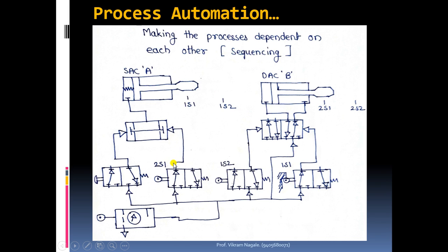I'll take you step by step to the final logic. Now what will happen whenever this rod end is leaving the position? What will happen over here? Since we have called this 2s1 and this is initially pressed, because right now you can see it's a 2D picture of the circuit diagram or system, the status of both cylinders is initially retracted, and for that initially retracted condition, this is the status of the limit switches and the controlling valves.